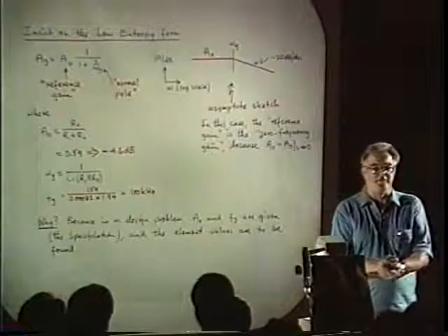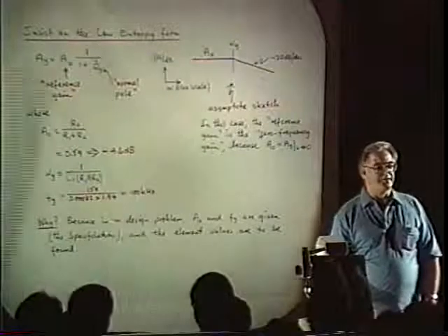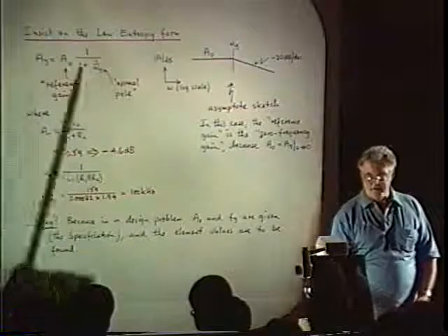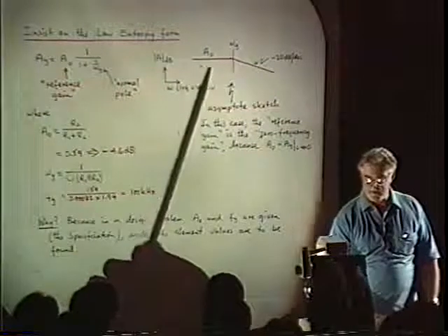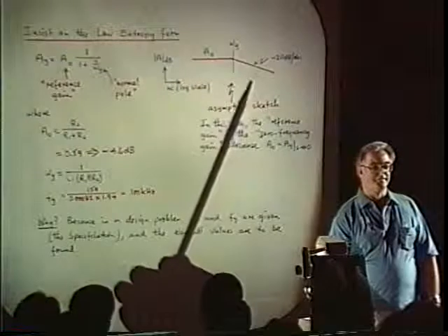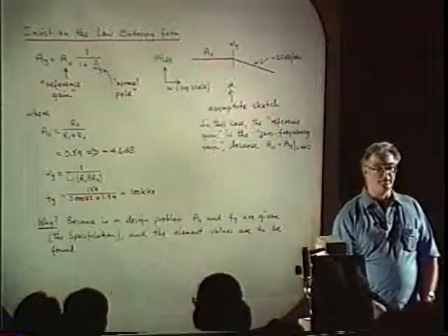You certainly don't have to plot it. This is a sketch. You can do it freehand. It contains all of the useful information about the shape of that function. All you need to know about it. These are the salient features: the flat gain, and in this case, a single corner frequency.